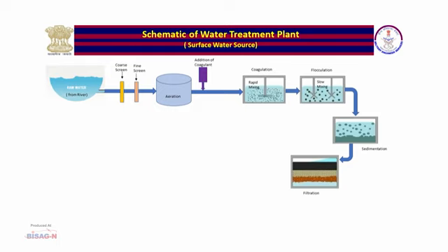Based on filter media and beds, they can be granular medium filter, fabric and matte filters. The granular medium filter can be single medium, dual media and multimedia, which is generally trimedia. Sand, coal, crushed coconut shell, diatomaceous earth and powdered or granular activated carbon have been used as filter media. But sand filters have been most widely used as sand is widely available, cheap and effective in removing impurities.